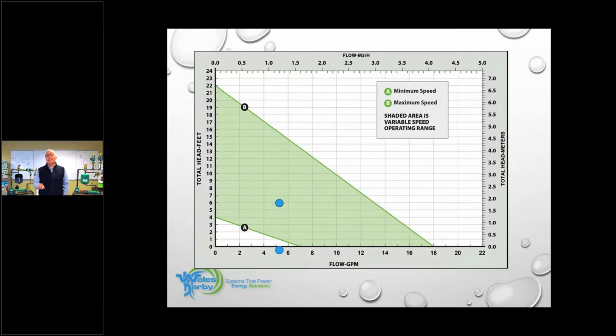So since this is a delta T circulator, this circulator now recreates a pump curve. So that's where it's going to perform, right there. All zones calling, that is where I'm going to perform, and that's what I'll deliver. So I'm nailing the actual delta T that I want for that system. As zones open and close, it'll change and create a new pump curve.